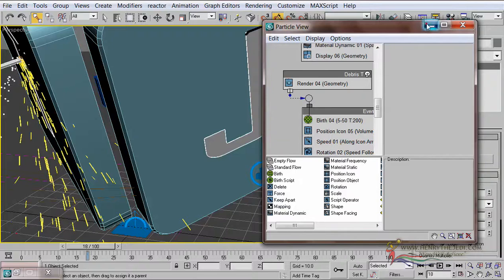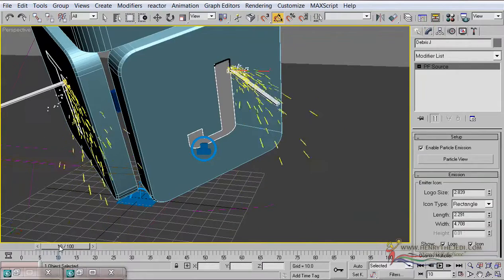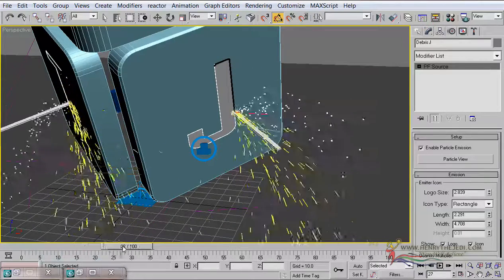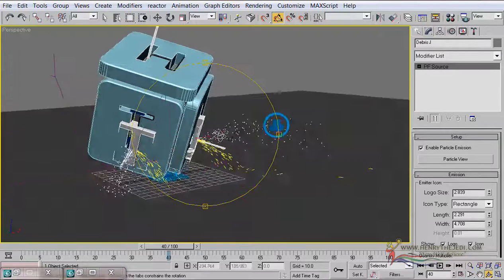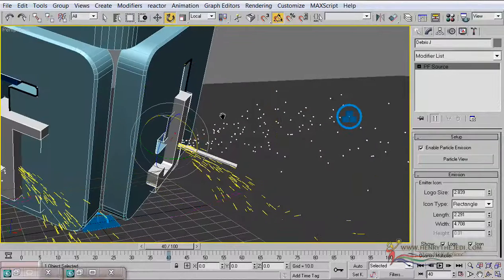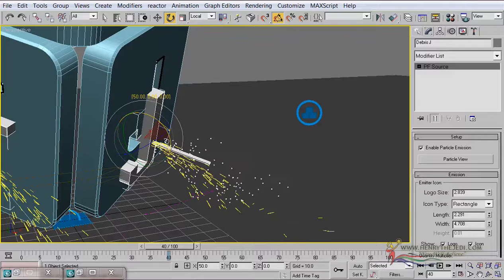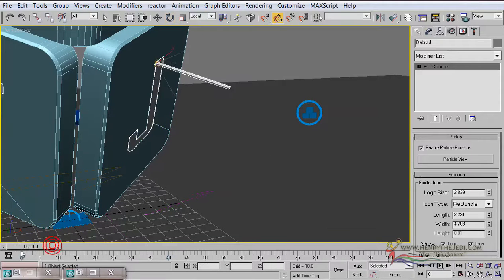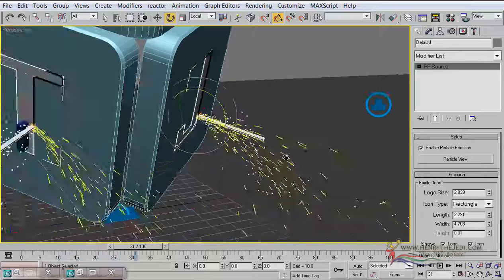And I can assure you now. Aha, there are the debris coming nicely. See that? Aha. Oh yeah. The question is, which direction are they falling? They're falling to the side. Well, simply select the debris J. Select the rotation tool and rotate it downwards on the local axis like that. So of course the debris are falling nicely to the ground like that. Brilliant, eh?